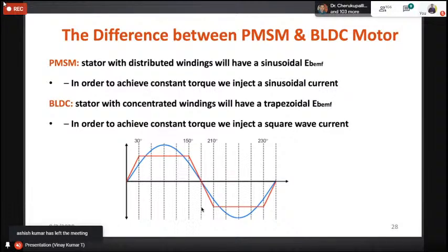So what are the conclusions? BLDC machine will not take sinusoidal current. It will take non-sinusoidal current. Non-sinusoidal current is nothing but a resultant current having other high frequency current components. Because of these high frequency current components, other communication signal electronic circuits will get damaged, right? That's why BLDC machine you can prefer generally for low power application.